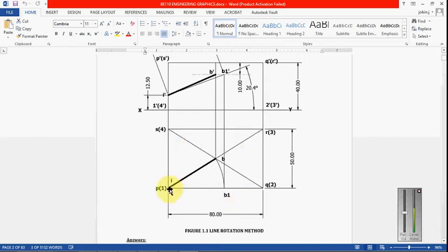The room consists of 4 corners, so there are 4 cases. Also there are 2 methods to solve this problem, plane rotation method and line rotation method. When you consider the image in this position, you can solve it by line rotation method or plane rotation method. Consider the image in this corner, again one plane rotation method and one line rotation method.